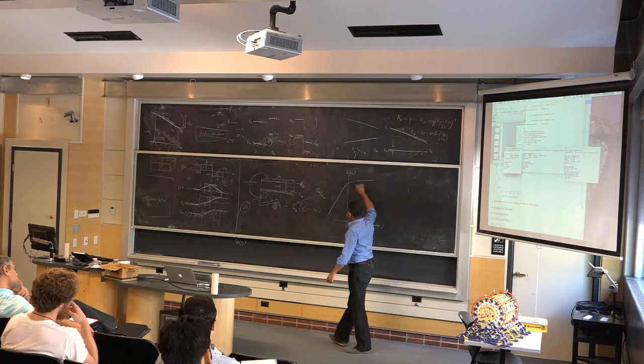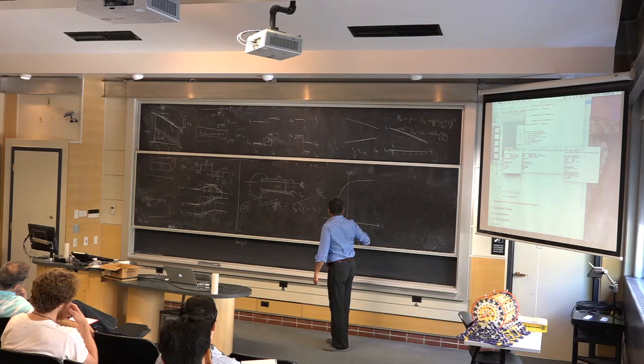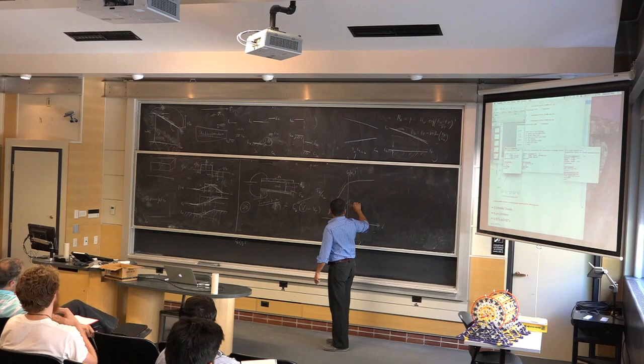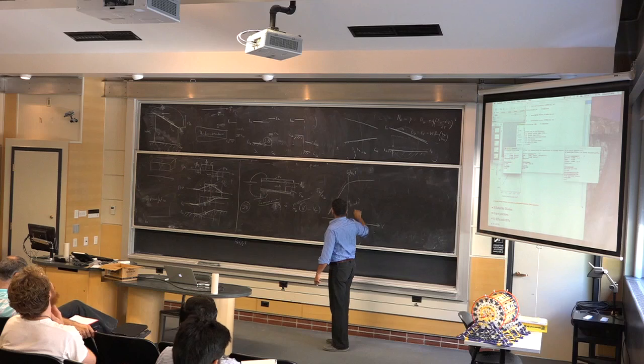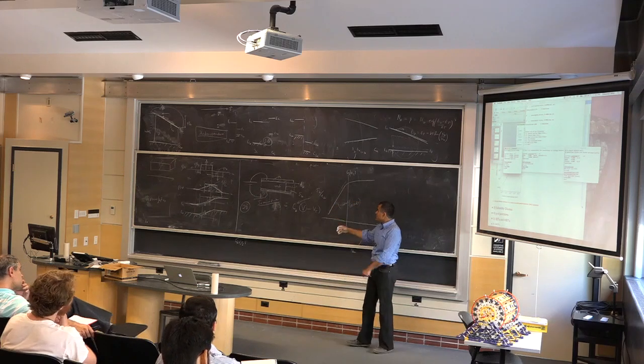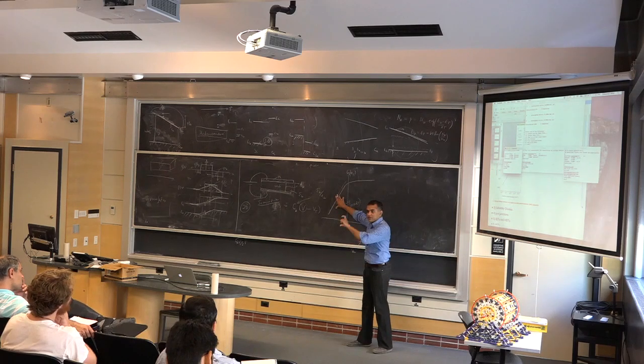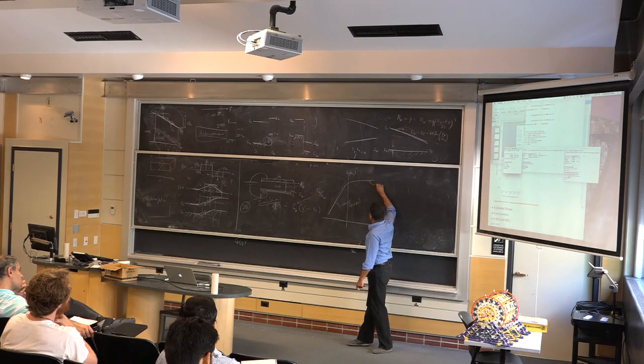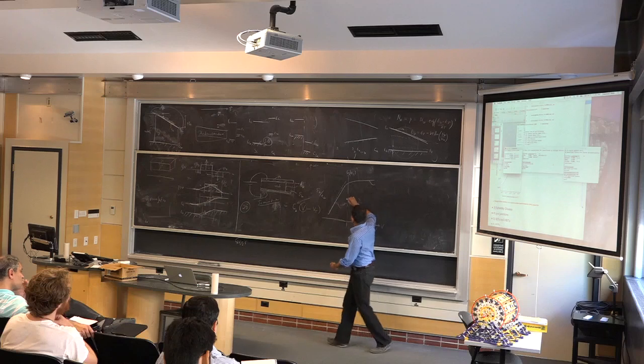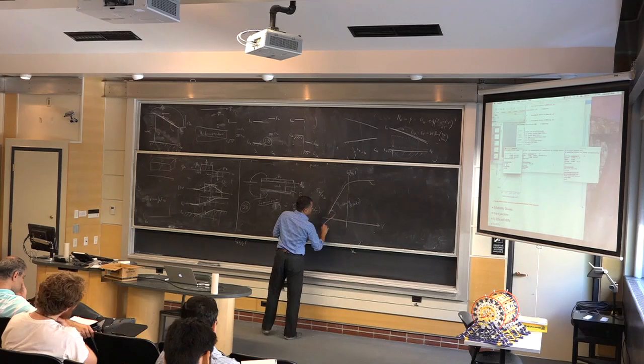Right? And this is actually the heart of a transistor and many other devices, PN junction, Schottky diodes. This exponential here, we'll see, will be close to what you call the 60 millivolts per decade. This is what it's going to look like. So it takes 60 millivolts to change the carrier density by a factor of 10. And the moment you reach here, it will look like some power law. In other words, let me just write this down and we end here.